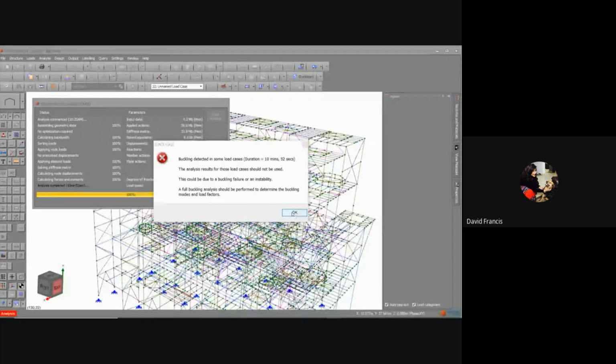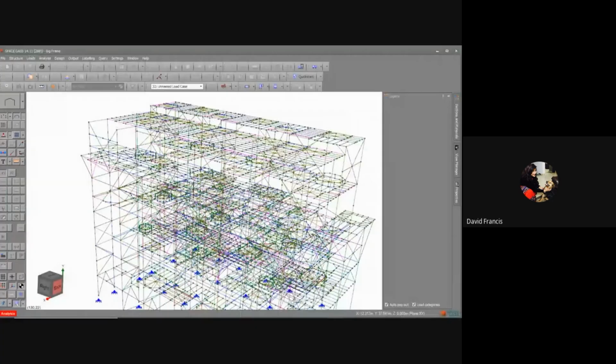So I can see that there are some issues. And of course, now I'd want to explore member 40, and I'd go into more detail. And then the frame would get to a point where I wouldn't have these messages, and then I would go into the buckling analysis as well. And we'll get a feel for that when we get into the workshop session later on today.